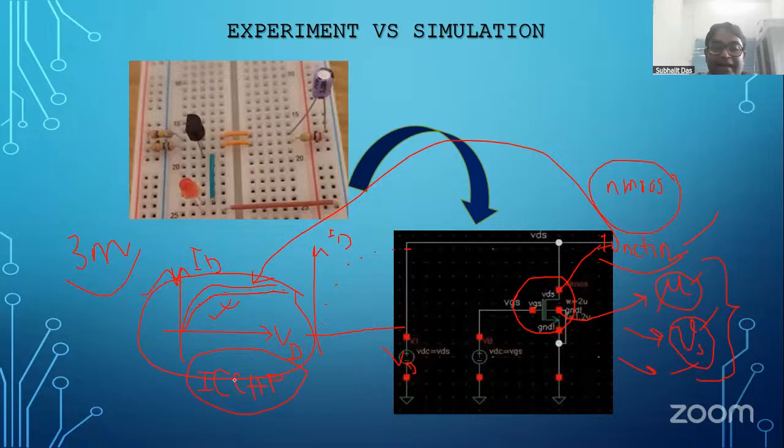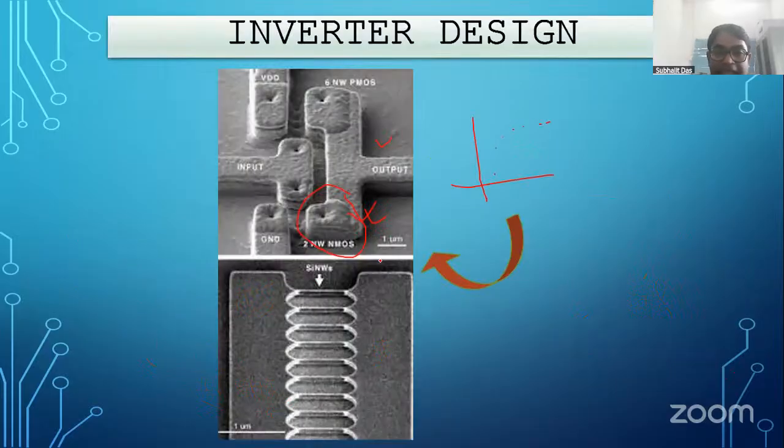This is done when all the characteristics like GM, GDS, output characteristics, and the transfer characteristics are similar to the experimental result and my program. Then I can tell that this MOS and this MOS are the same. So this MOS is now a dummy of this MOS.